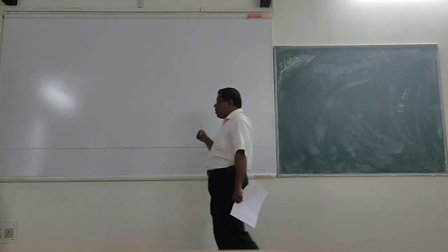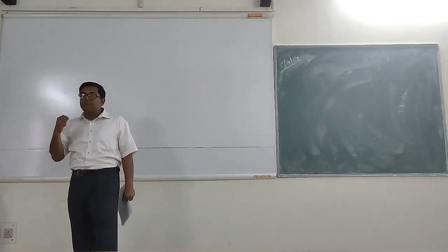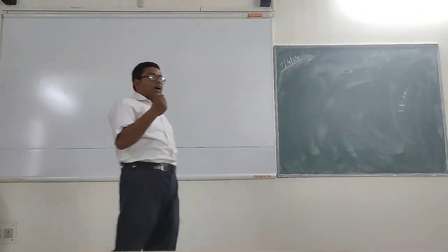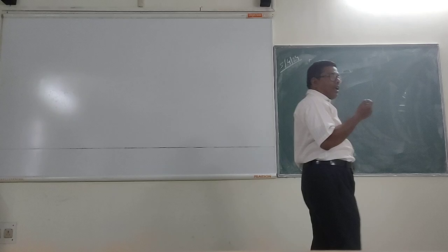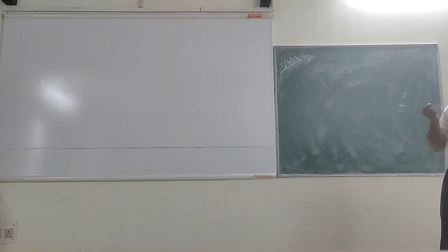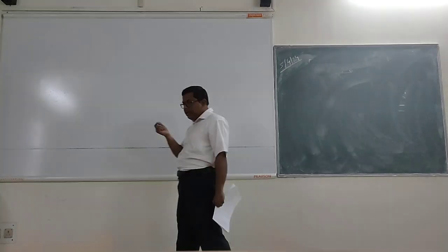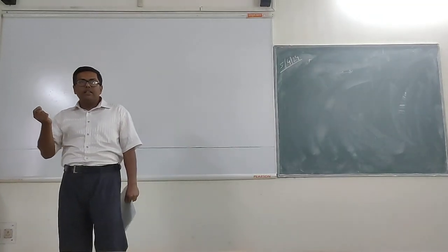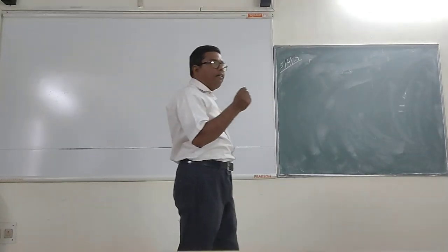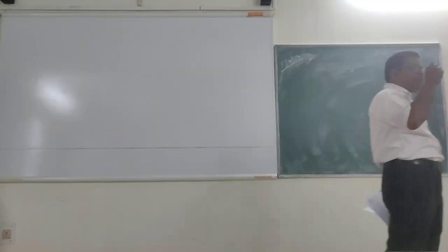So how can we define some permissible deflection? If you see different Indian Standard codes like IS 456 or IS 800 for concrete and steel respectively, you can see that different deflection criteria are mentioned there. Okay?